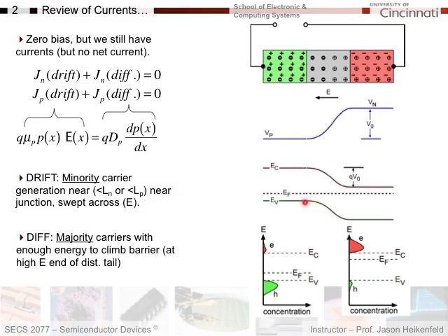And then we said the other type of current we had going on all the time for this device was diffusion current. We have a very high concentration of electrons on this side, right? Very high concentration. But the problem is that if they are down at energy levels below the contact potential, they can't get over this barrier here. This is an energy barrier, right? And so only the electrons which find themselves up here, higher than the energy of the energy barrier, will be able to diffuse across from the high concentration on this side to the low concentration on the other side.